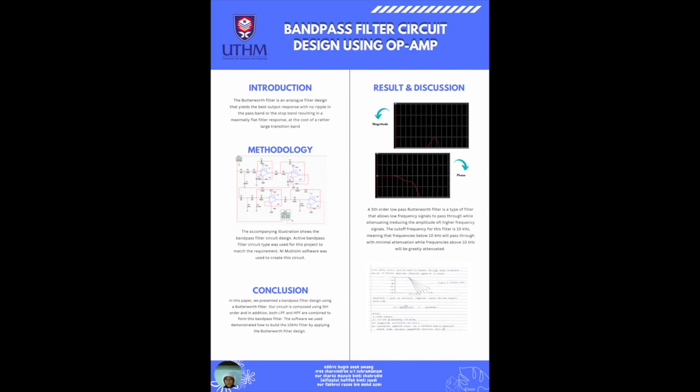As the order of the filter increases, the quick roll-off around the cut-off frequency also improves. Its phase delay is largely frequency dependent. The delay meant here is the delay time experienced by a signal's various frequency components when the signal passes through a linear time-invariant system. What is meant by frequency dependent is that different frequency components experience different delay. Next, I will pass this to my groupmate Sri Shavindran for the next part.